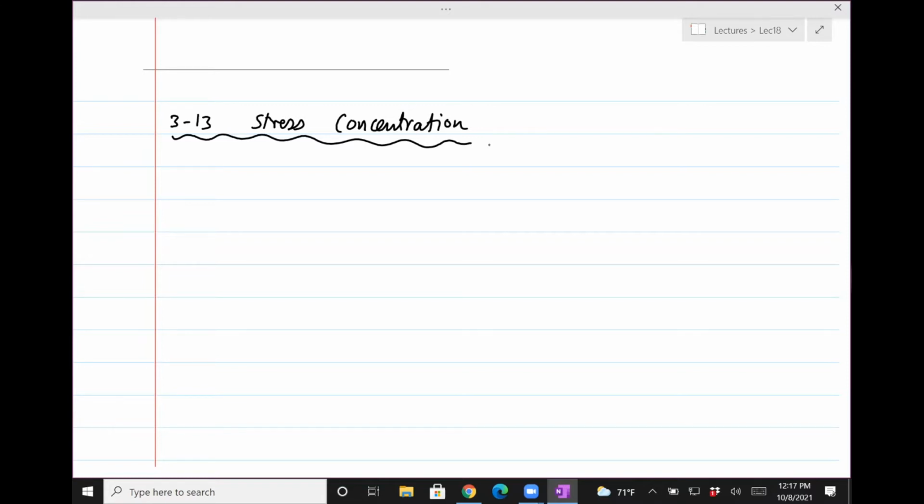And the reason why the stresses are higher is because when you make a design for any mechanical element, you don't necessarily end up with a uniform design having a regular shape like a circle or a cuboid. You have things like grooves, corners, shoulders, edges. All these things introduce stresses because of the change in geometry, and that's the focus of this part.